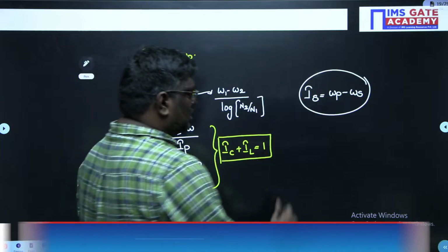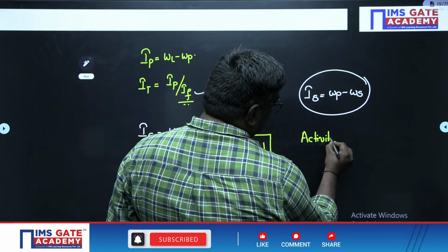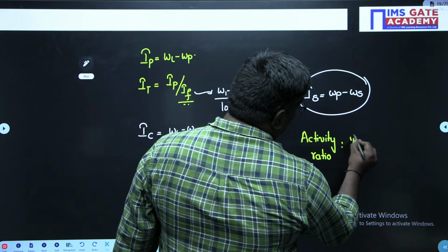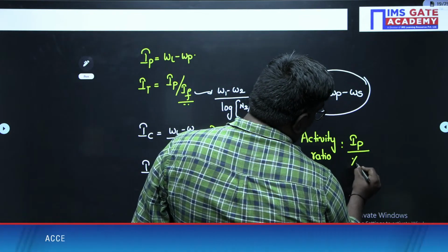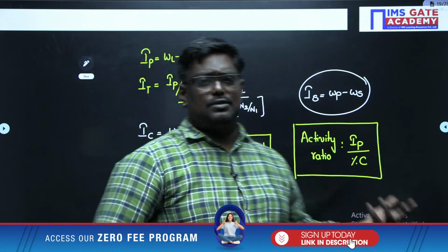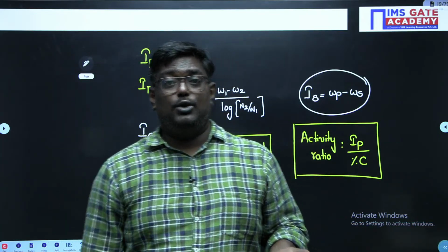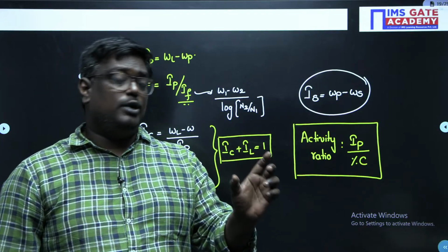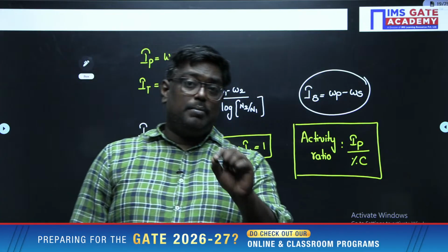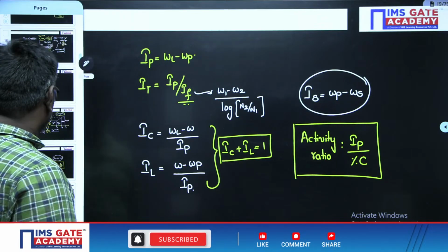In addition to this, you should also have an idea of activity ratio. What does activity ratio mean? It is the ratio of plasticity index to percentage of clay fraction. We want to learn about activity ratio because the swelling and shrinkage potential of a soil can be judged by it. If the activity ratio is less than 0.25, we take it as low active; 0.25 to 1.25 as medium active; more than 1.25 is highly active. Remember, montmorillonite has a value up to 4, which is a very highly active soil.